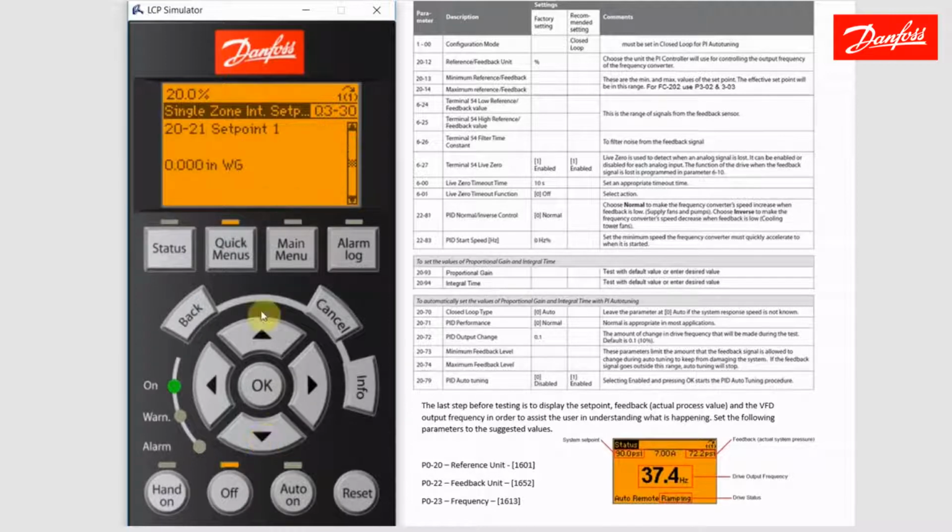Moving on. Here I can enter directly into the drive my set point. I'm going to enter 2.5 inches of water gauge for my set point. That's right about halfway on our transducer scale. Of course, it's important to make sure that your transducer covers the range where your set point is at. So 2.5 inches.